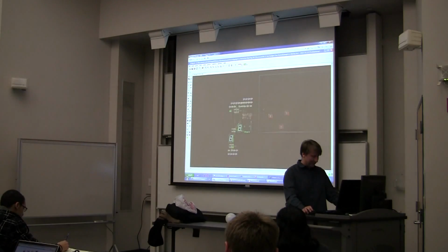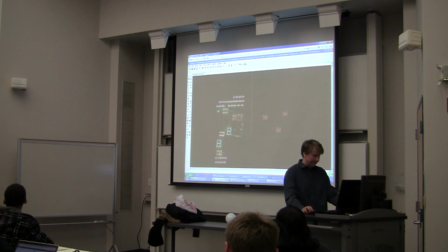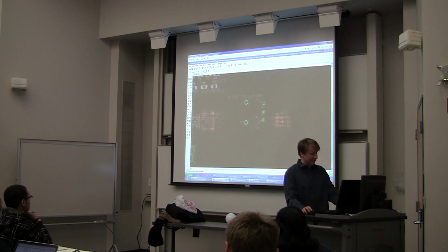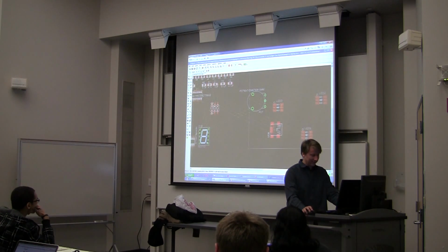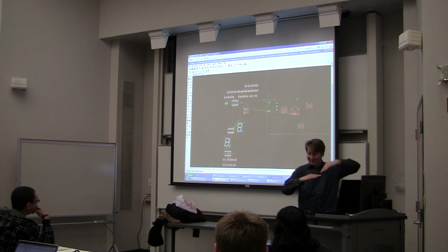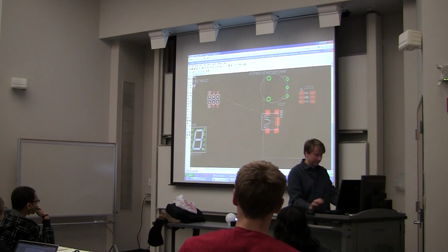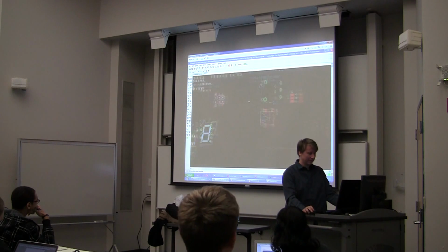So now let's go back to our board. Oh no, we have more resistors. And here we go. Now, and then you get to arrange things. And then things like the potentiometer, remember, you kind of want to have it sticking out the side of your board. USB does not work if you point the business end of it in the middle of the board. You can't plug it in. It has to be sticking out the side, basically flush with the board. Maybe a little over if you're paranoid.